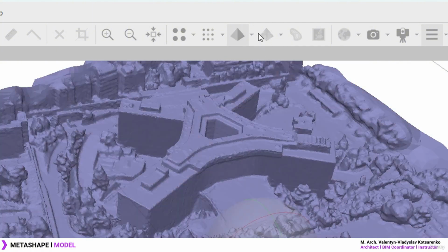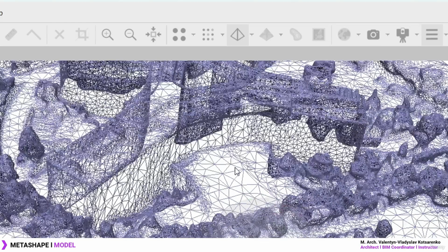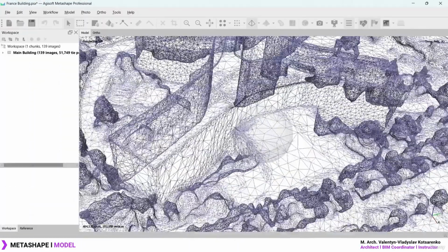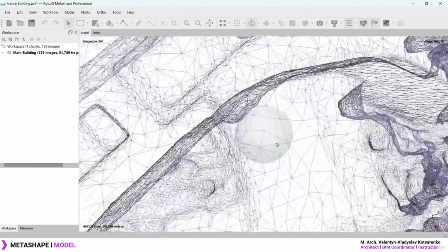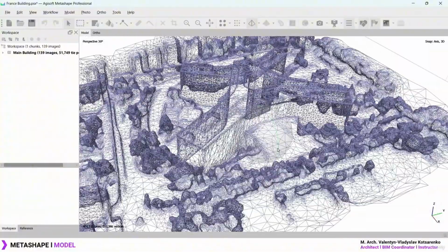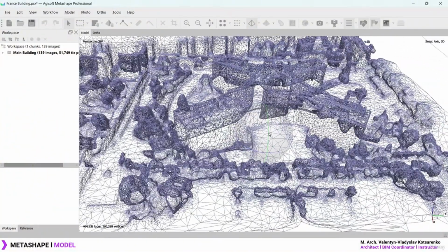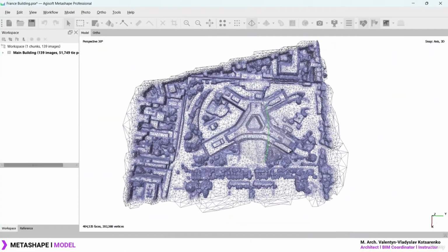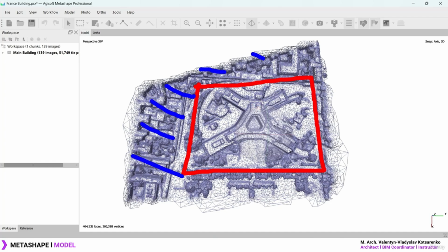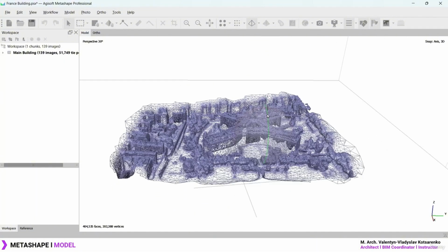You can activate the solid model, you can activate the wireframe one. This is where you can now visualize the triangles, okay? So you can see that some areas are going to be much denser in triangles, some are going to have a lower triangle count. So it looks interesting, promising, and this is the reason why when you export this model into ArchiCAD, it's definitely going to lag a little bit. So usually what I like to do is filter out the triangles a little bit more. I usually only cut out the interesting part and delete the rest. Okay, so it's a matter of configuring this.